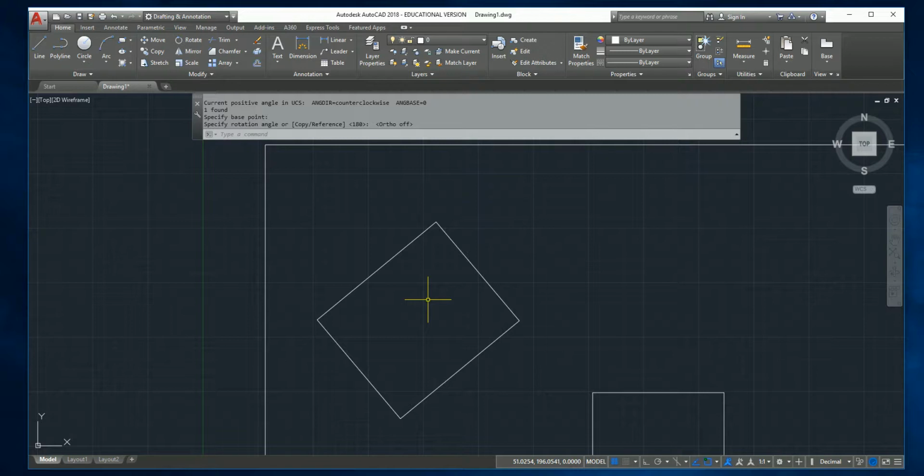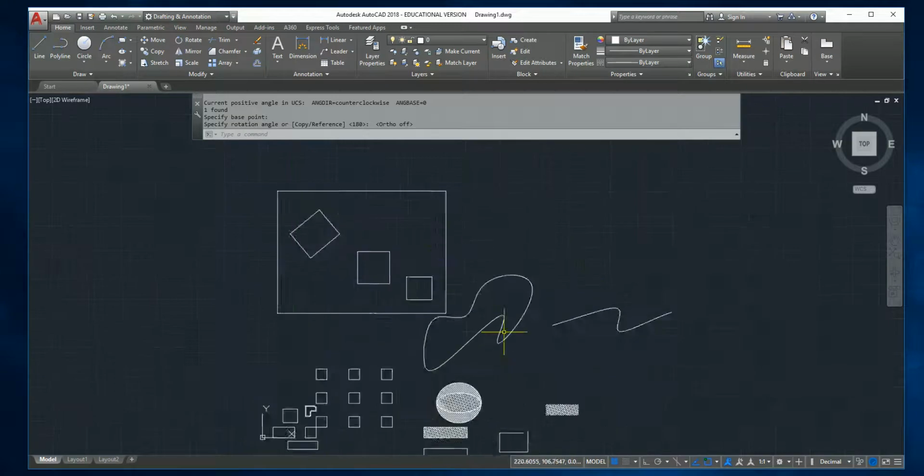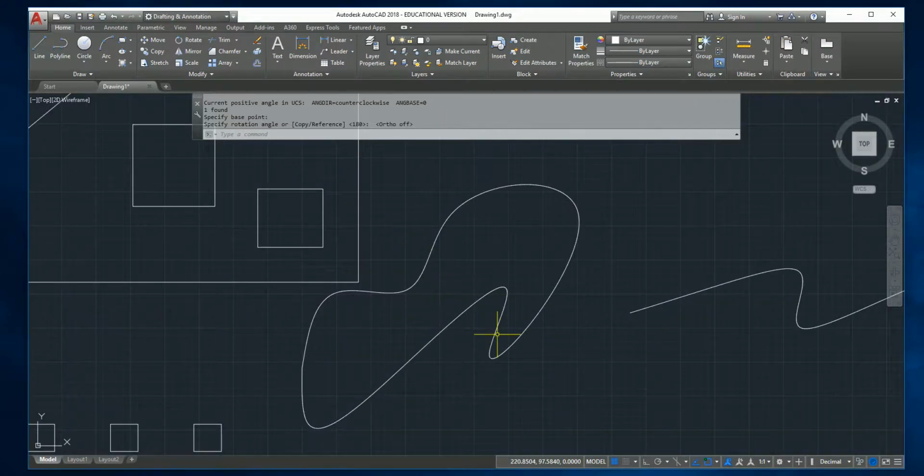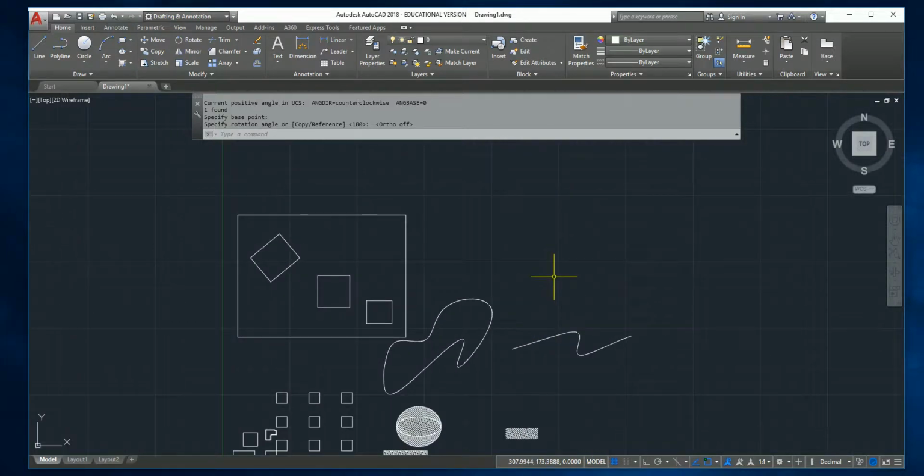I can understand why ortho has to be off when we do the squiggly. Right, exactly. When you do the spline, if you have ortho on, it's just going to draw a straight line. You could get it to curve if you go hard enough vertically, but not nearly like this shape. So, again, construction lines, they're awesome.